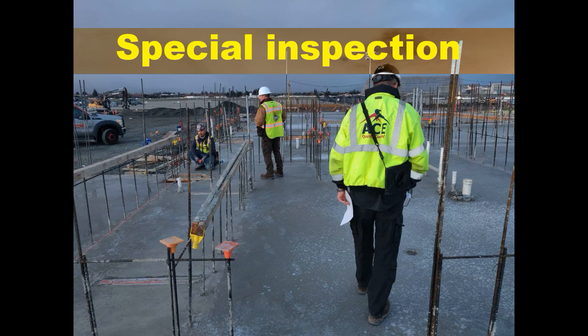Special Masonry Inspector Qualifications Requirements. Inspector must have ICC Structural Masonry Special Inspector Certificate with 1 year of related experience, or Registered Professional Engineer with 3 years of related experience. Make a copy of the Special Inspections Project Manual available on the job site during construction. Submit a copy of the Special Inspections Project Manual for approval.